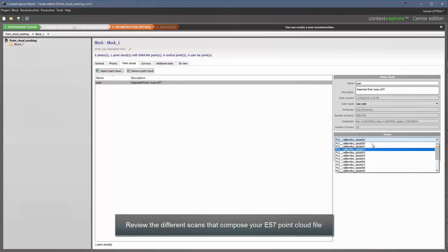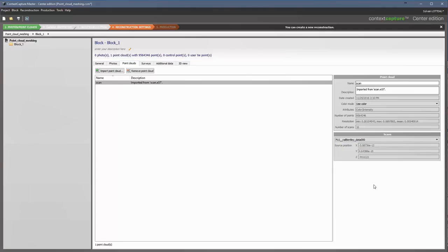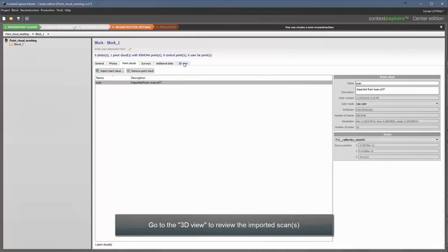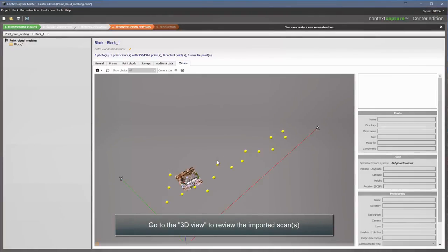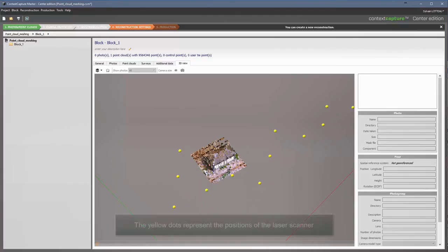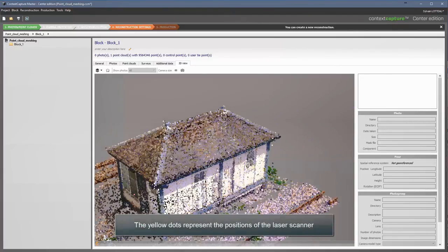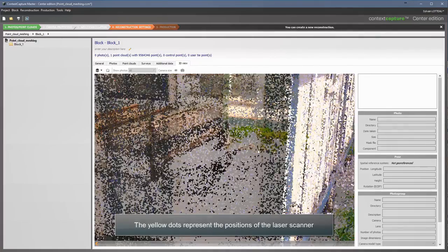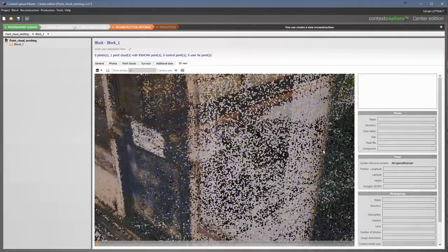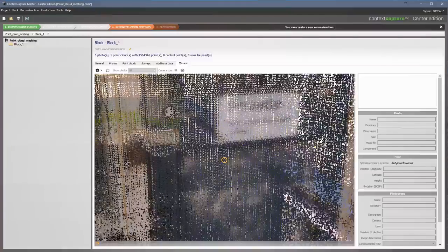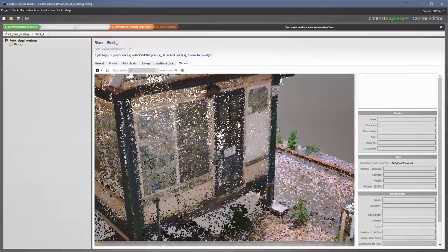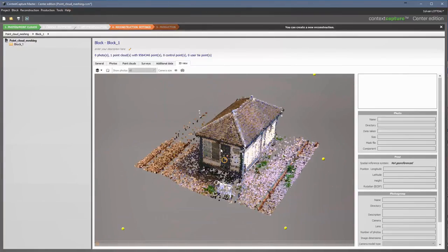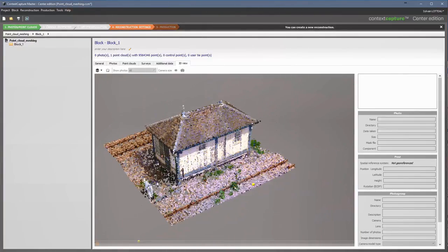We can also see each scan world that was captured and its location during the scan. That's important for us. We see those yellow dots are representing where the terrestrial scanners were. Now for this demo, we're just focused on this building. Now I know you're seeing just a few dots and looking through this. That once again is from the point cloud, how they are just a series of dots, and if they're thinner, you can actually see through them, which is why we want to combine the photogrammetry with this.